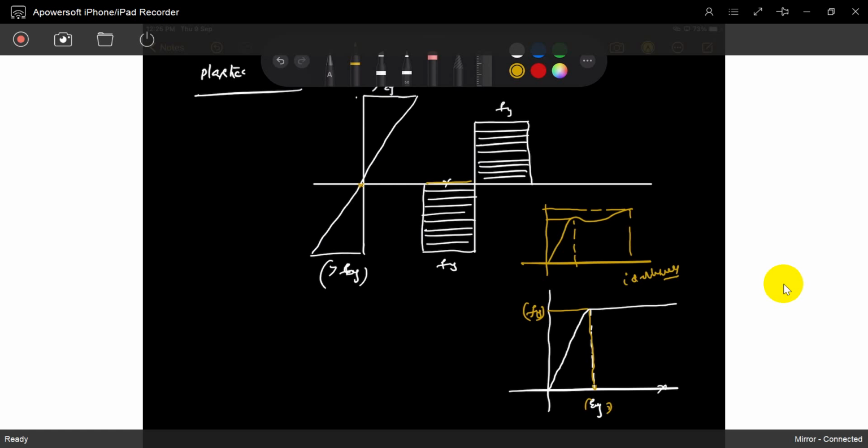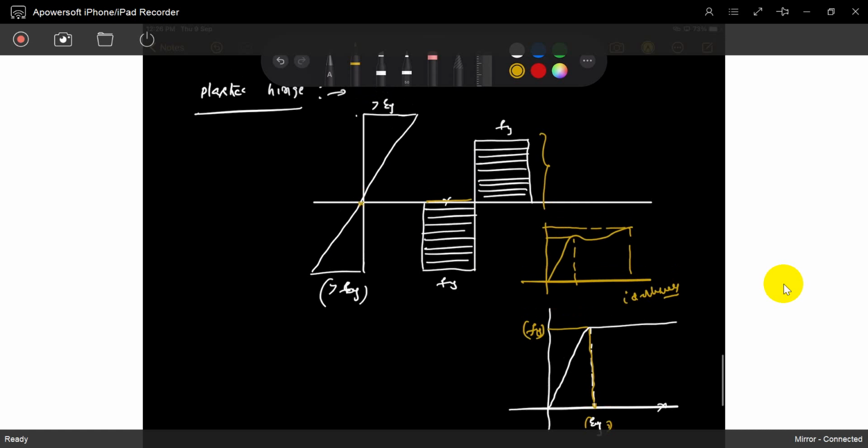So take a rubber or some maida dough. If you stretch the maida with a very small force and just hold it, it gives so many deflections. That means there is no increase of force, but with a very small force the strains keep increasing. So when every fiber reaches the Fy, the total section's strains abruptly increase with a very small increment of force.